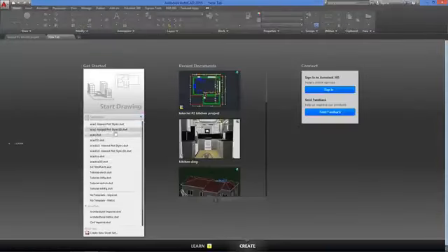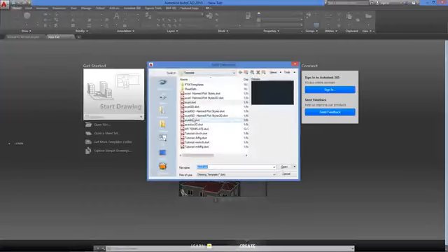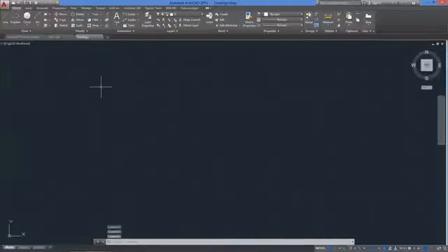Now let's click New from the Quick Access toolbar to see that in CAD, templates are identified by the extension DWT. A CAD template will have a lot of predefined settings to minimize the time setting up the drawing environment. For example, if in your country you use the metric system, you select the AutoCAD ISO DWT. But if you're in a country that uses the imperial system like here in the United States, we will use the AutoCAD.DWT and then we'll click Open.